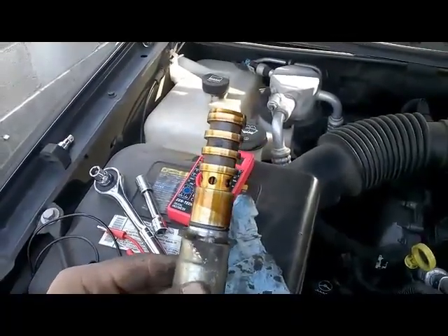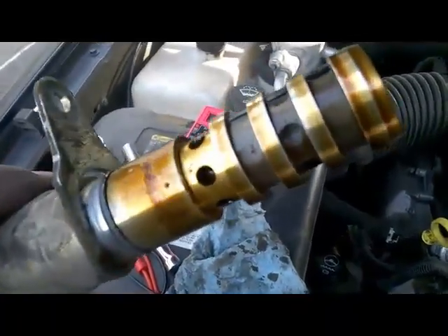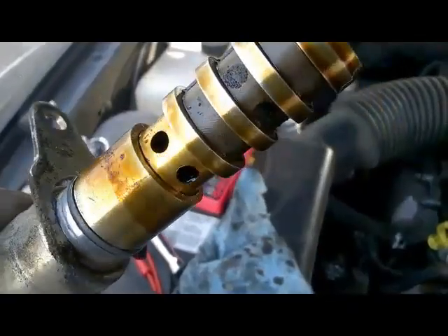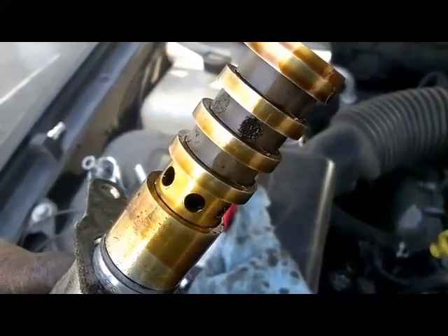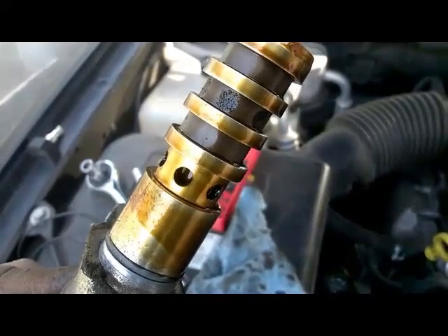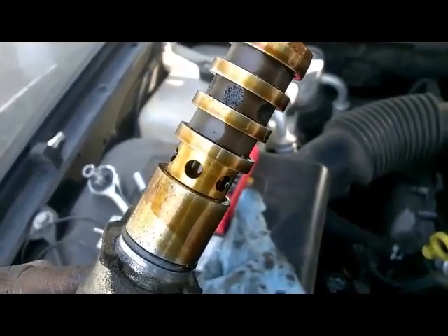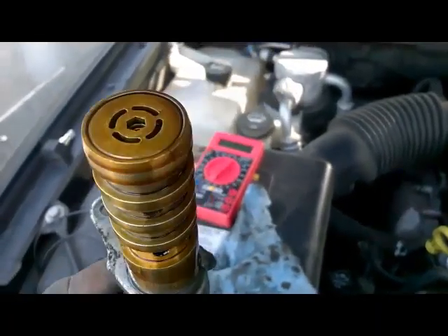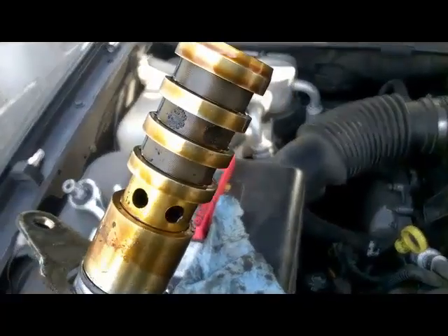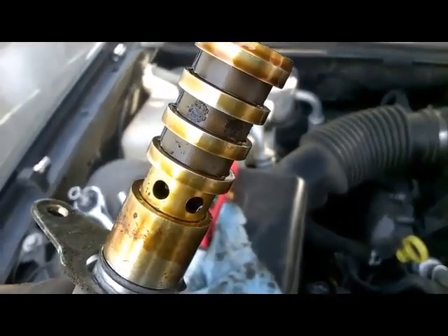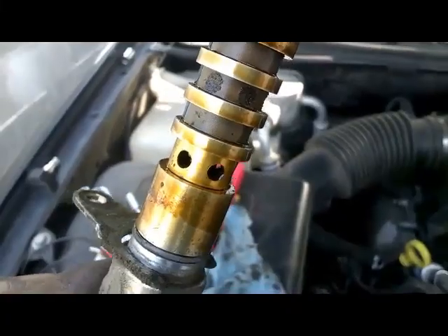All right, guys. So this is the camshaft actuator solenoid. It already came off, and we have evidence that our screens, which are right there in the middle, are clogged up with oil debris. So this is causing our P0014 code on this engine, and this is pretty much the reason why this engine is running rough during idle or during low speeds. So basically, this confirms the reason why this code is on is due to these dirty screens, which are restricting the oil flow to this camshaft actuator solenoid.